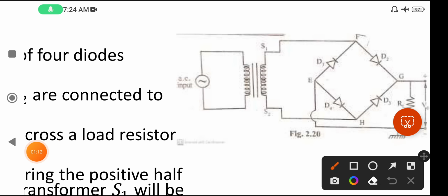And when it is positive, see here, this positive is connected to the P side of diode D2 and the N side of diode D1. So it is positive, and for the diode D2 this side is also positive. So that is why it becomes forward bias. That is the reason. And next come to D1, where this positive is connected to the negative. So when positive is connected to negative, it becomes reverse bias. Okay, that is why D1 is reverse biased.